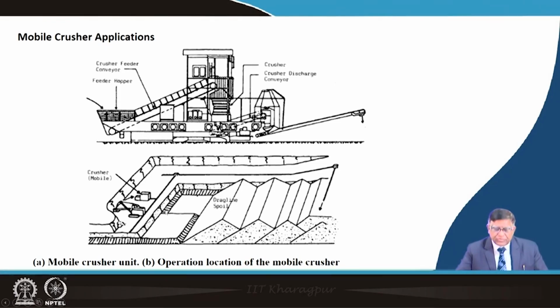So, now say there are two benches here, you can see this is one bench of overburden, and then there is another bench of overburden, and then they expose the coal. Now, this overburden bench is being excavated by this dragline. This dragline is sitting over here, and the overburden is removed and then placed over here. So, this is just a phase layout of a mine when you look from the top with an in-pit crusher location. This is important for you to note here.